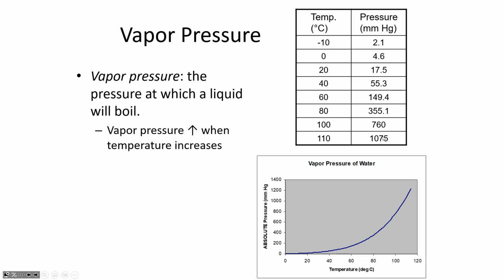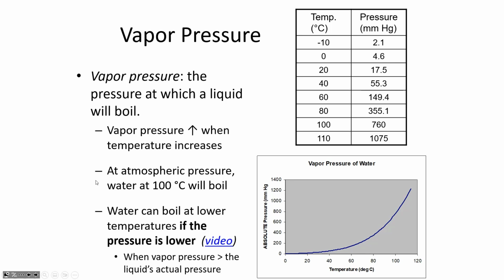So if the absolute pressure of the water in the venturi got below the vapor pressure, then it would begin to boil. Not because it's hot, but because the atmospheric pressure that's resisting the vapor pressure is equal. So you can get water to boil by raising the temperature, or you can get water to boil by reducing the pressure. Either one will cause the same effect.